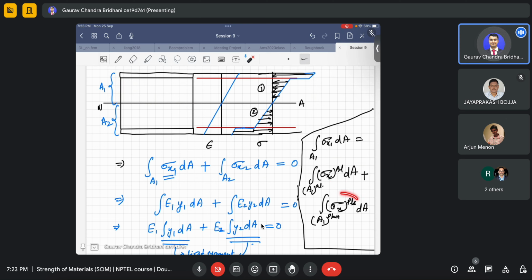You can find the plastic area using that k d. Then you know how much is remaining, this is nothing but d by 2 minus k d. Only this much is aluminum. So, this distance is d by 2 minus k d, and you can find this aluminum also. So, you have to actually put the limits of integration. If you are going from this direction, you will put k d to d by 2 for the aluminum case, or for the plastic case you will put from 0 to k d, correct?